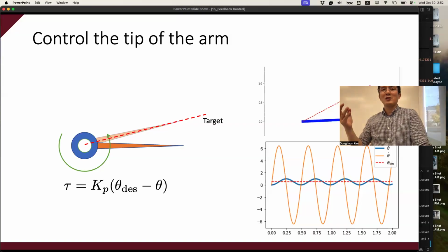What is the potential energy? The equation for the potential energy is 1/2 k theta squared, right? If the desired neutral is 0. So it started from that potential energy, then it switches back to the kinetic energy, potential energy, back and forth without losing the energy. And how should we lose that energy?